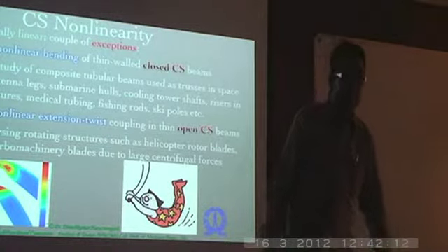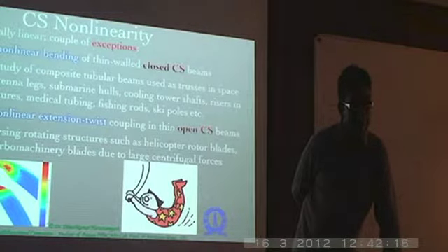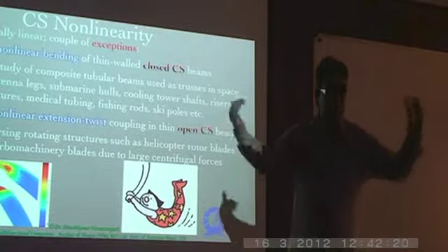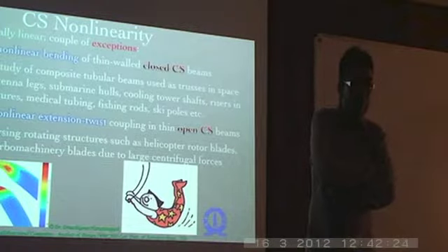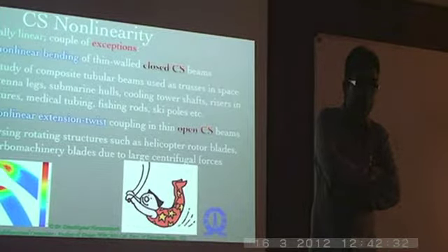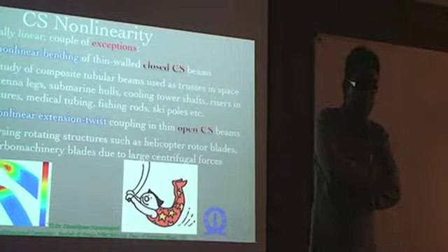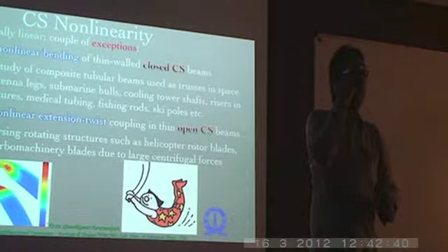In case if in a beam we apply a moment, any cross-section which we analyze, the moment will be the same. So that kind of it's okay. If it's a pure bending moment. Pure bending. Right. In case if it's a point load at some point, will there be any difference when we analyze a cross section at a point where load is not applied, and there is only moment due to this load, and that cross section at which the load is applied? Will there be a difference between these two cross section analyses?